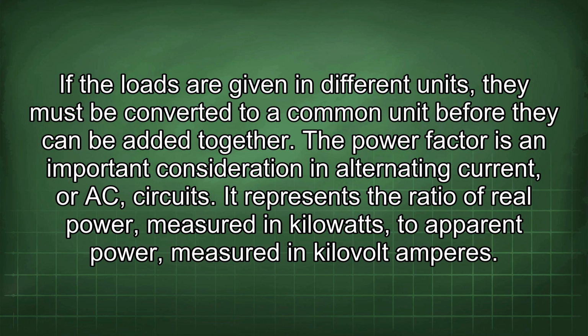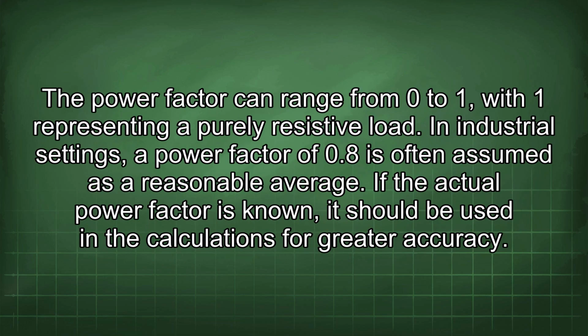It represents the ratio of real power, measured in kilowatts, to apparent power, measured in kilovolt amperes. The power factor can range from 0 to 1, with 1 representing a purely resistive load. In industrial settings, a power factor of 0.8 is often assumed as a reasonable average. If the actual power factor is known, it should be used in the calculations for greater accuracy.